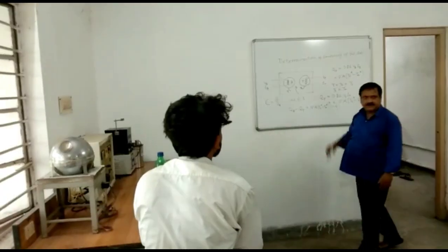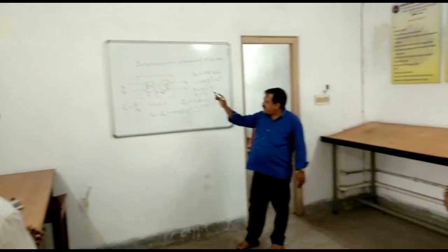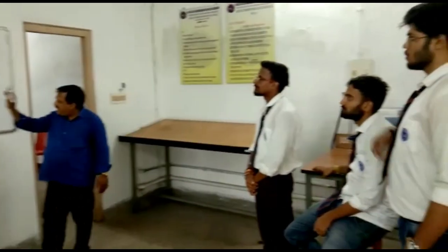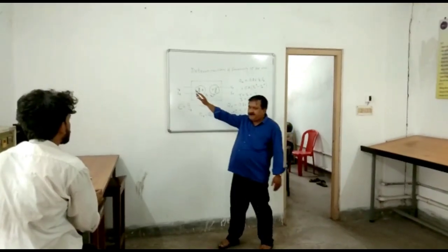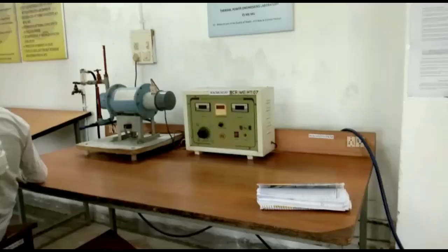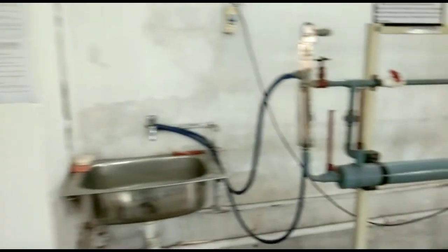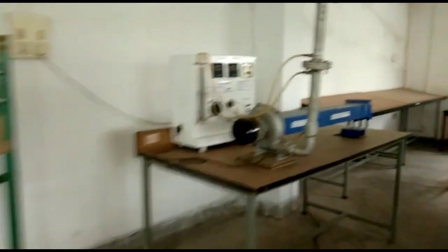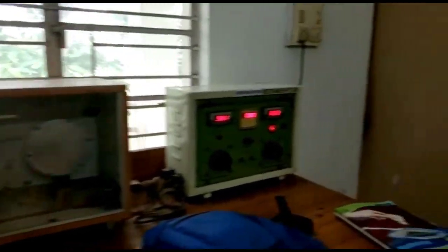Working in this institute since 2014. My research interest is in the area of thermal engineering, fluid mechanics and renewable energy. Both the plates are connected with some heaters, and you can heat the plates, and it is VT and IV. For the test plate it is VT and IV. You can measure the temperature T1 for the black plate and both the plates' temperatures are the same. Then only you can start.